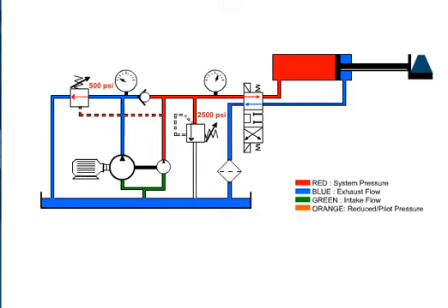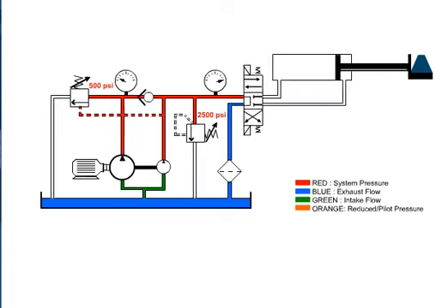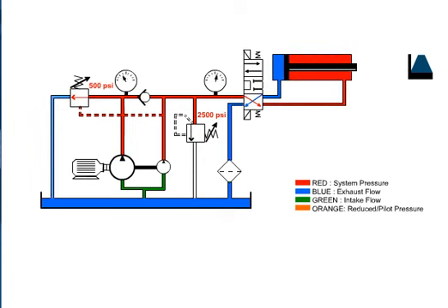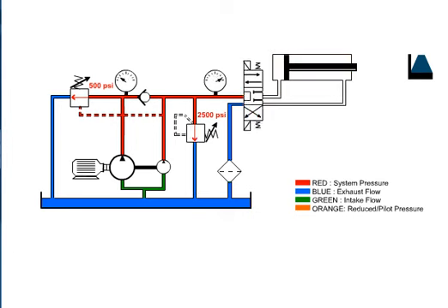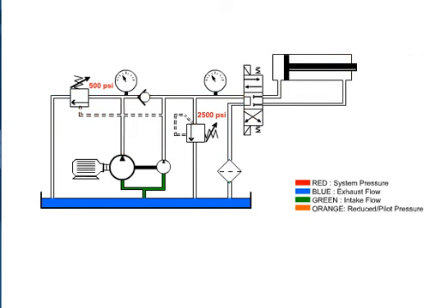The pressure will continue to rise until it reaches the relief valve setting. When the directional control valve is reversed, the pressure drops and the unloading valve closes. The cylinder would retract at a rapid speed. Now let's examine more closely the components that make up this system.